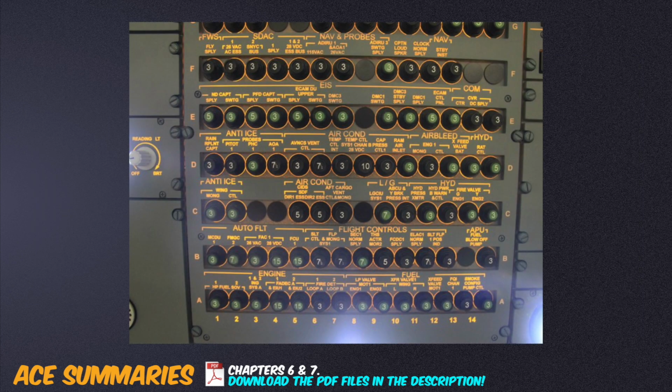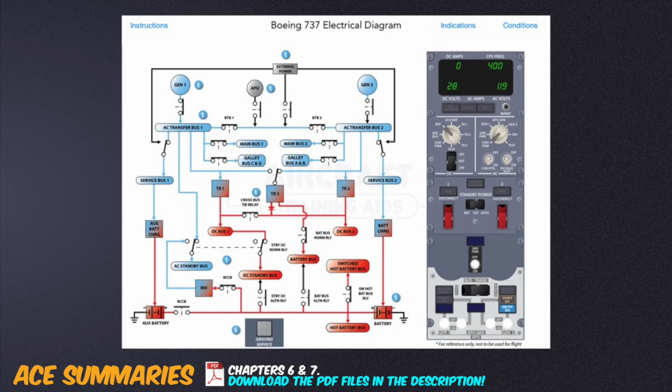An aircraft should carry at least 3 fuses of each type used, or 10% of the total number of each type of fuse used, whichever is greater. Circuit breakers can be non-trip free or trip free, the former of which allows you to manually keep it pushed in during an overload condition as an emergency measure, even if that may damage the electrical system which the fuse is designed to protect. AC power is advantageous as it can be generated using alternators, which are simple in construction.